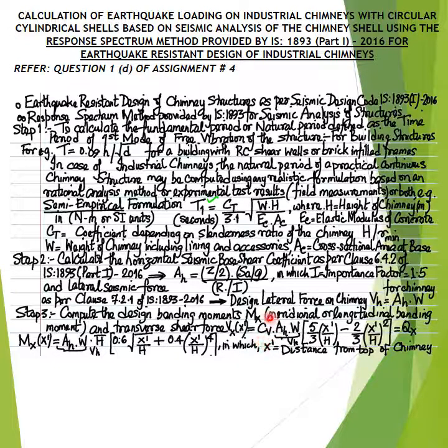and the subscript V therefore denotes the shear force, and the notation C subscript V signifies the coefficient is for the calculation of the transverse design shear force V subscript X. As a check, one may verify that substituting a value of the coordinate x dash, that is the distance from the top of the chimney, equal to the total height h of the chimney, into the formulation for the design transverse shear force Vx,